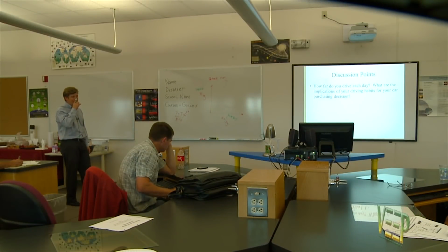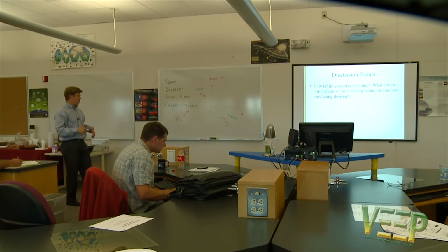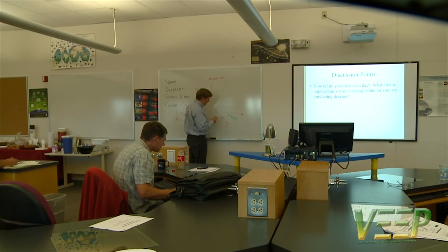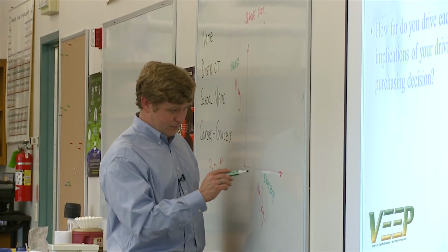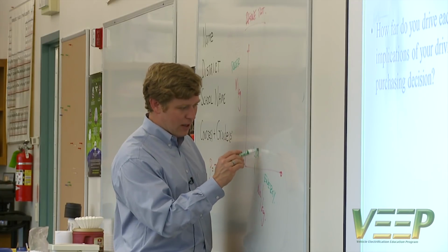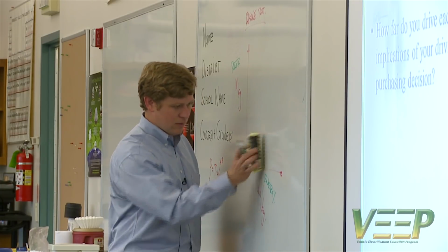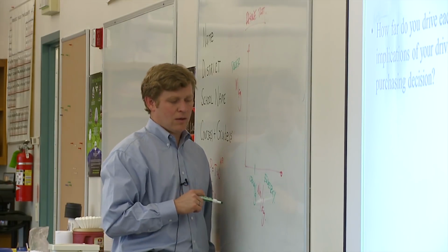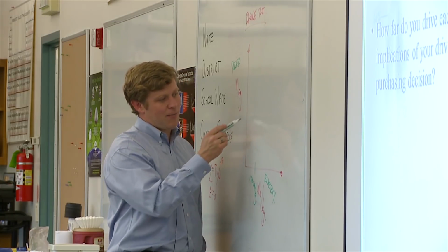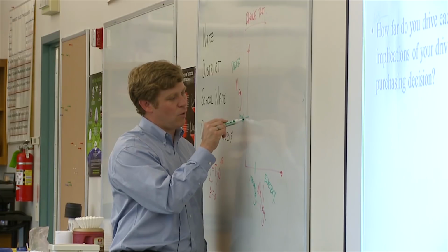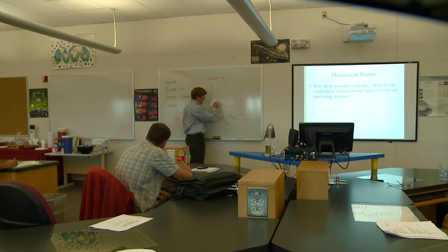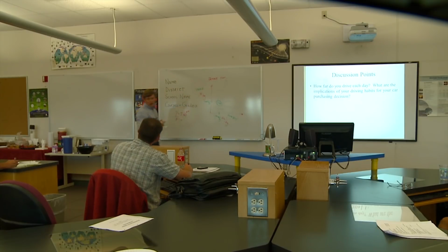So for instance, a conventional lithium-ion battery, like the kind of thing that would be in the Volt, is going to operate at about, let's say, on a good day, 150 watt hours per kilogram, and at a power of about, let's say, 1,000 watts per kilogram. So if I was to draw a blob, let's call this lithium ion, it would look about like that.